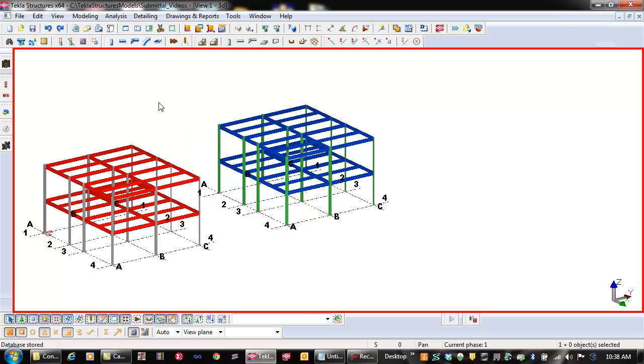By compartmentalizing the piece marks of building 1, the shop can order material, fabricate, and deliver to site all of those pieces while waiting for the detailer to release building 2. Once building 2 is released, all of the piece marks are their own separate marks, so that way it doesn't cause revised shop drawings or revised quantities to anything that was previously released in building 1.